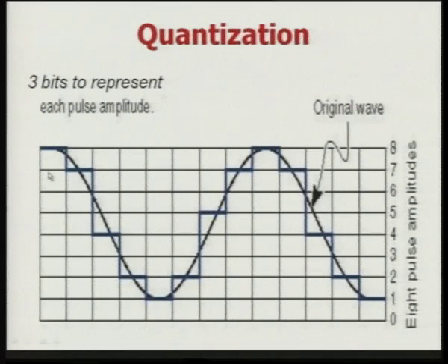Okay. So, you can see that when I do the sampling, whatever sample I have taken here, until I come to the next sample block I maintain the same value. Over here I maintain the same value, now I come to the next value and maintain the same thing, until I come to the next block. So, the digital signal that I get has discrete amplitudes.